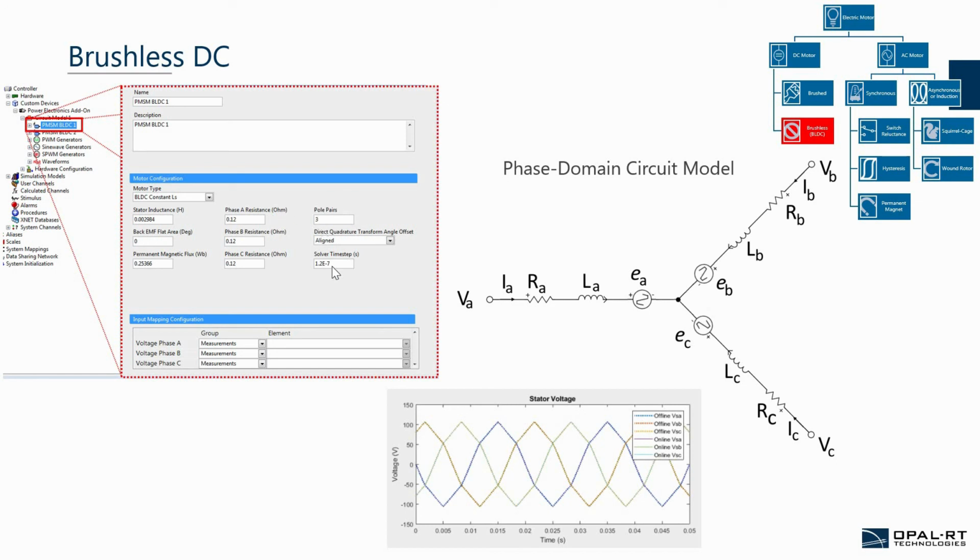Of interest is the back EMF that the BLDC creates. In general, BLDC motors typically have a trapezoidal back EMF, while PMSM motors have a sinusoidal back EMF. The shape of the motor's back EMF is important because it determines what type of drive current and commutation method should be used.